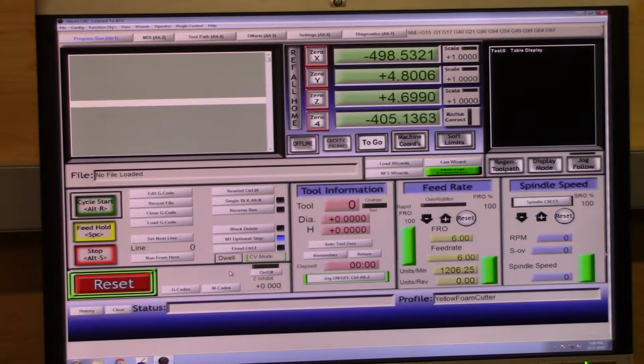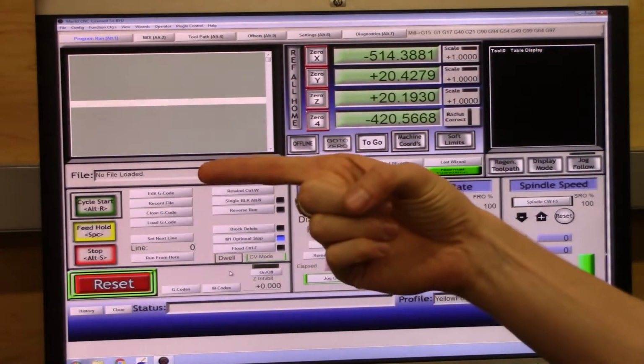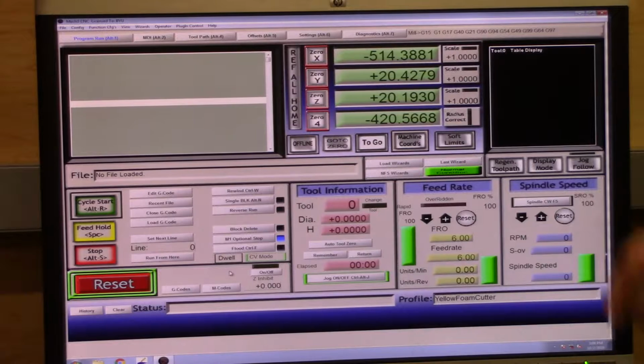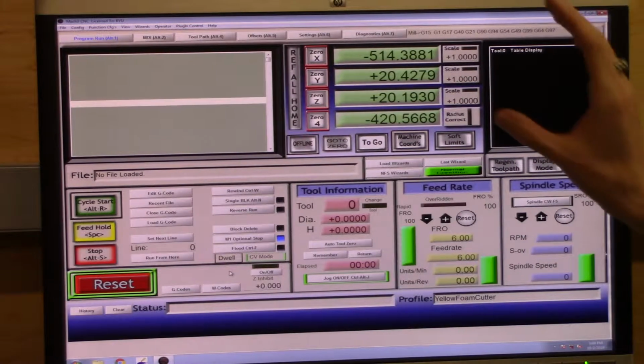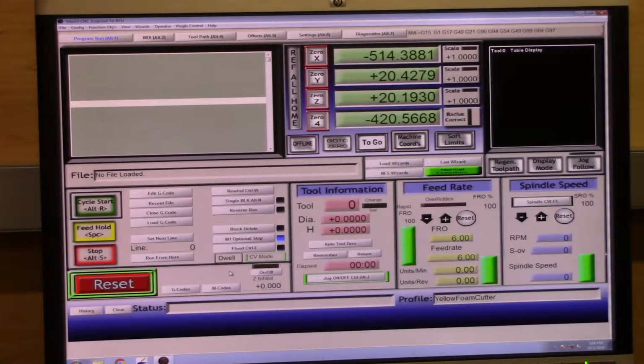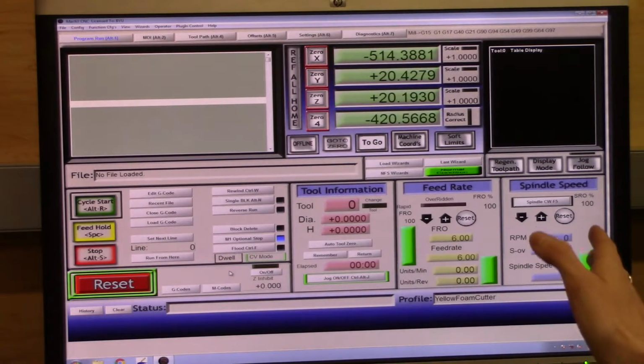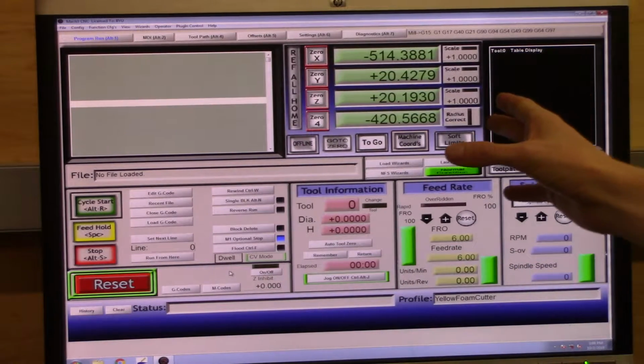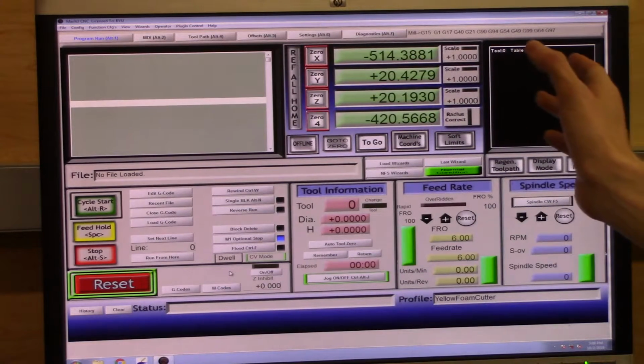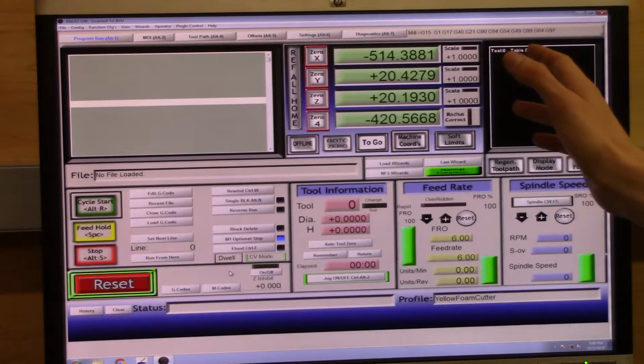So if I click on those, you'll both hear them moving and see them moving, and those values up there will change, and the stepper motors will also change. We're going to focus in on that in just a second, but I want to make sure we understand that. Before we place our foam block, we have to make sure that our foam cutters are centered. Oftentimes when the program is closed and reopened, like I just noticed here, the foam cutters were actually set to an X value on both carriages of 400 millimeters.